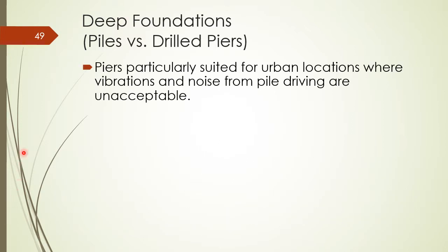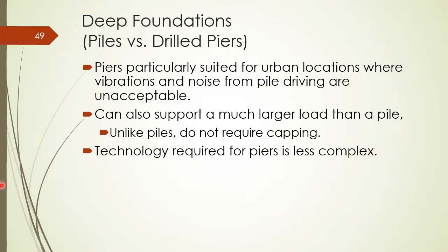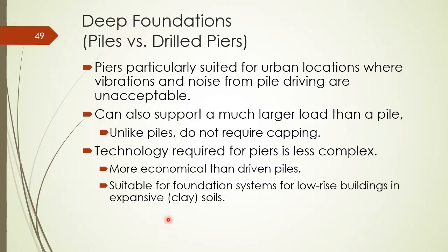Piers can be used in urban locations. Again, vibrations and noise. They can support a larger load than a pile. They do not require to be capped. And the technology, however, for piers is less complex. Again, there's that trade-off with cost, more skilled labor, and those areas. Piers can be more economical and, again, suitable in expansive soils.